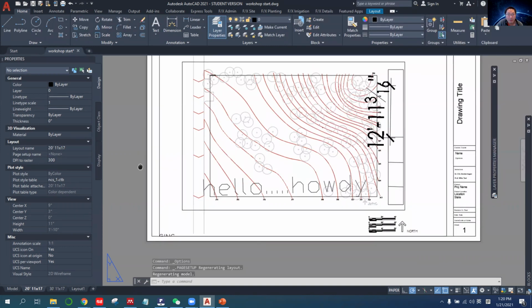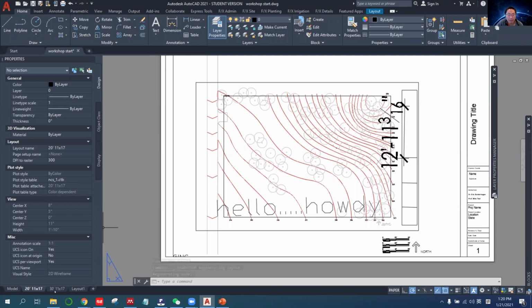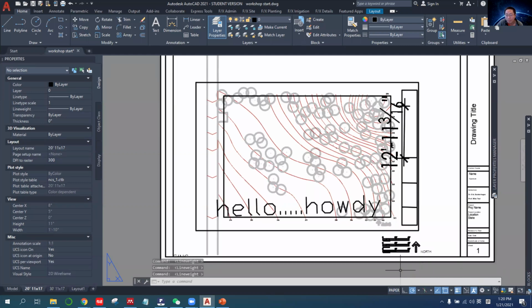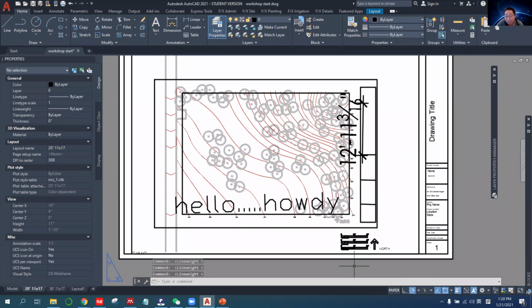So basically, what's showing up in the layout view is going to look exactly the same when you print them out. Even the line weights, they're gonna show the line weights. See, if I check the line weights, they can show the line weights. So that's the best practice I personally use. Make sure you have these line weights checked so you can see different line weights. Okay.